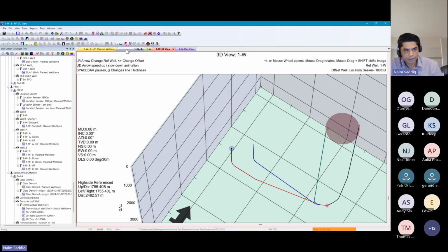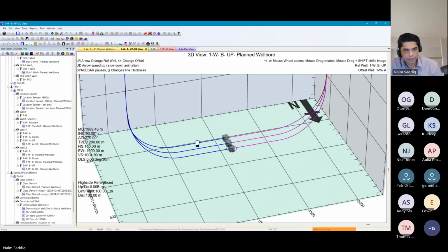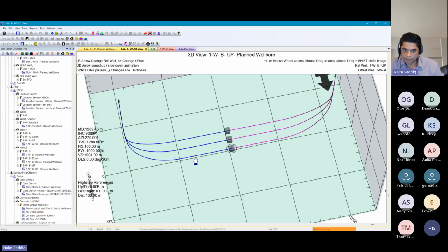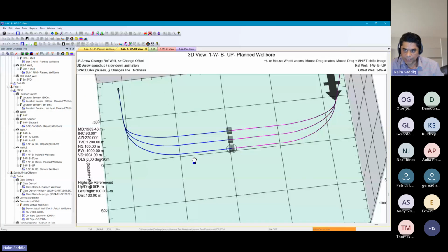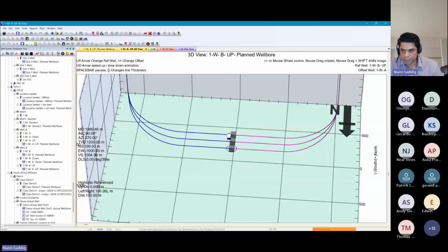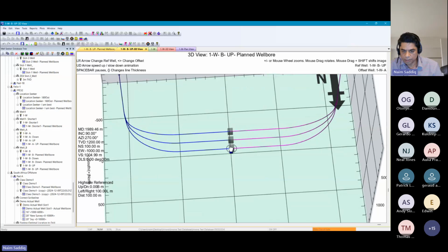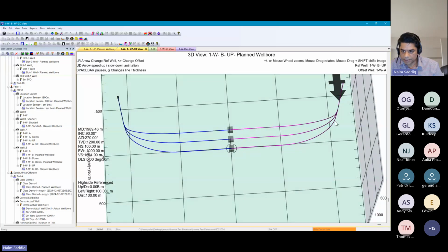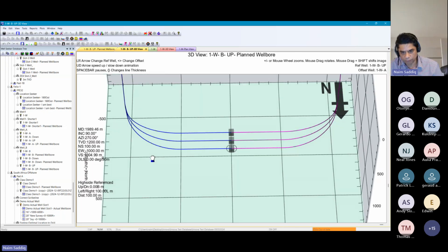The other thing I would like to show is the closed loop geothermal wells. You have two wells, 2 kilometers apart. They have side tracks meeting and combining. One is the injector, one is the producer. You can optimize where you will kick off, how far you will be, and the length of the horizontal part, and all kinds of design you can do here in this software.